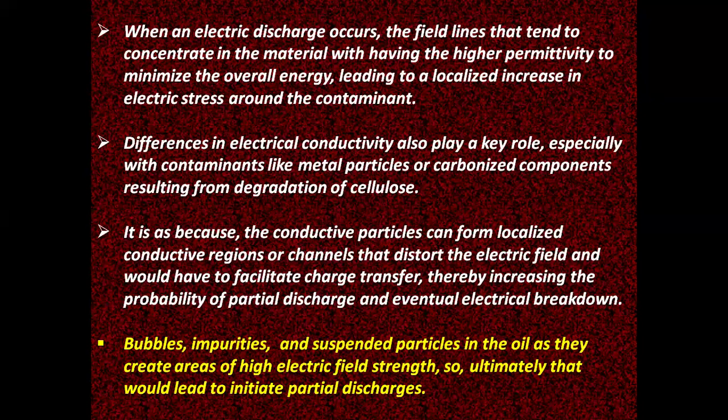Bubbles, impurities, and suspended particles in the oil create areas of high electric field strength. So, ultimately, that would lead to the initiation of partial discharges.